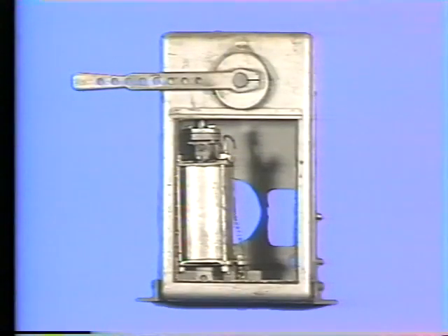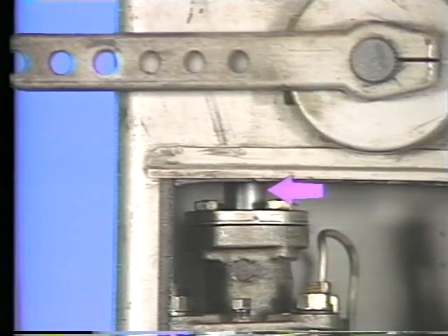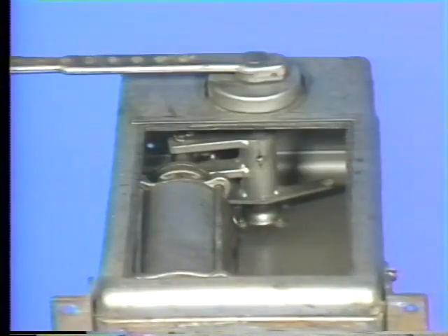In a piston actuator, air pressure acts on a piston in an airtight cylinder to develop thrust and produce movement, which is transferred by a metal rod to the final control element. In this case, the metal rod, which is the piston rod, is connected to a linkage arrangement that adjusts the position of louvers in an air duct to change air flow. The linkage and louvers are not shown here. The piston rod is connected to the final control element at this point.